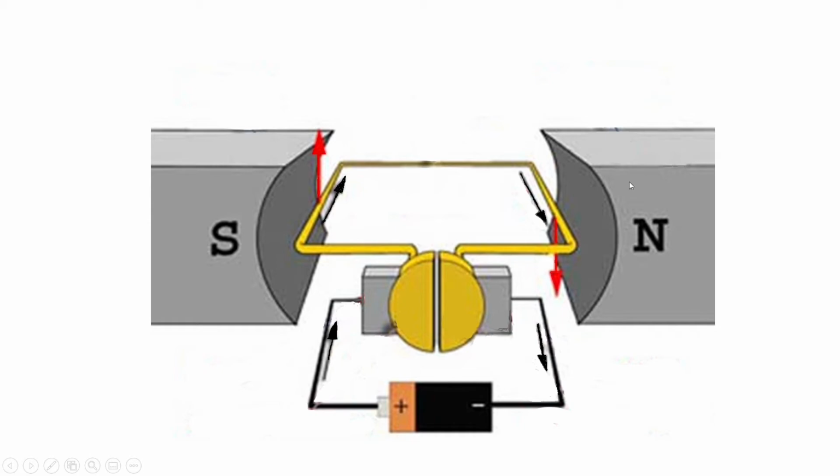So in our electric mirror we have a permanent magnet motor; in fact, we have two for each mirror. One motor will make the glass move up and down, and one makes the glass move left to right, or we should say that one motor controls the vertical movement and the other motor controls the horizontal movement.